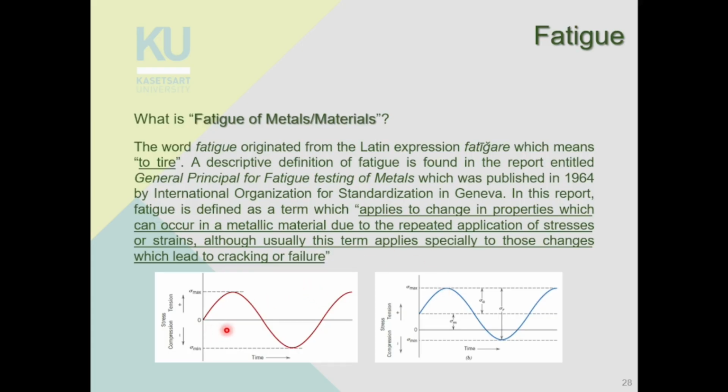You can think of it as the sinusoidal application of stress. Say for example, you start applying positive stress, which is tensile stress, up until the maximum stress, and then decrease the stress until you are not applying any stress at all, until you start to apply compressive stress until you get the minimum stress, which is the maximum compressive stress, and it changes again. So basically, the stress is not constant. You keep changing the stresses all the time, from tension to compression. You change the magnitude of the stress as well. When you do that, the material will get tired, and it will break.